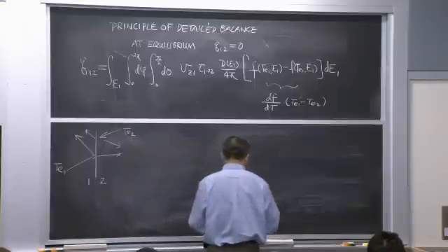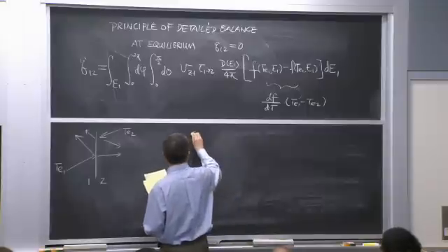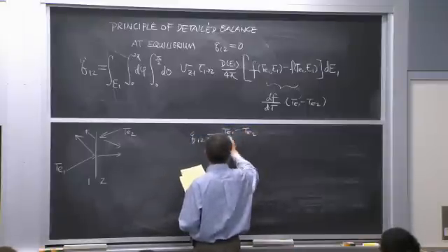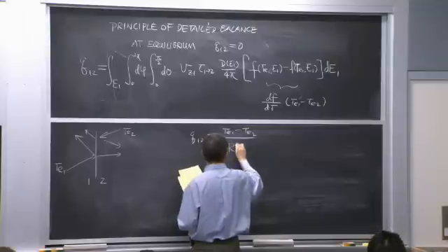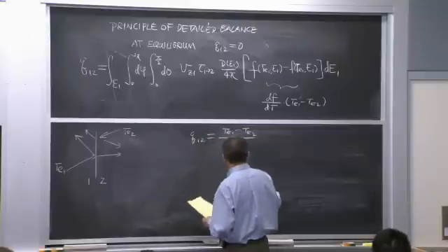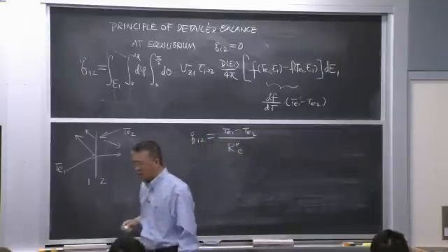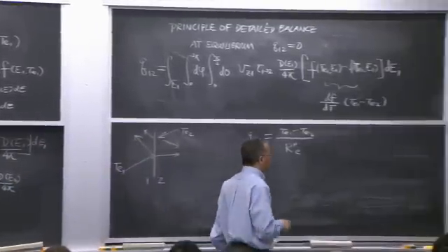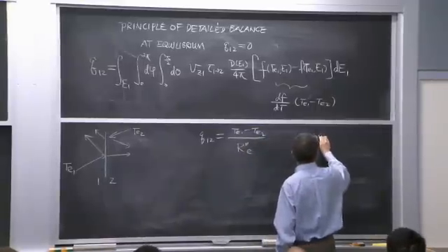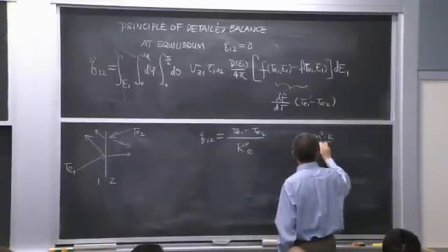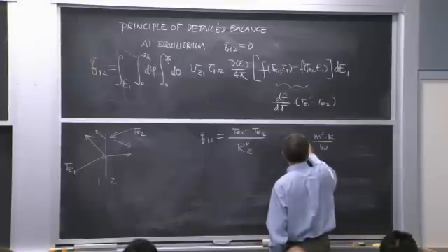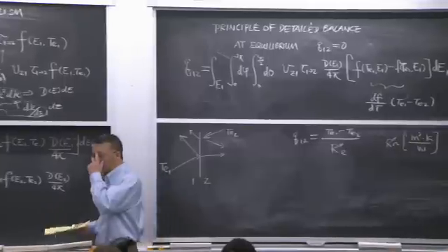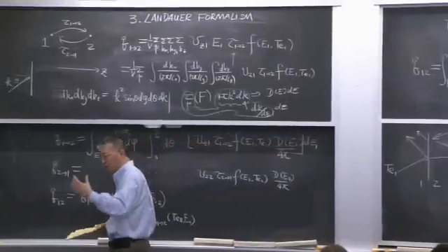And this Q12 equals TE1 minus TE2 over R prime. And let me also put this as RE double prime. That's a specific thermal boundary resistance. So the unit here will be meter squared Kelvin per watt. It's specific, per unit area. So if you know the area, you divide by that.